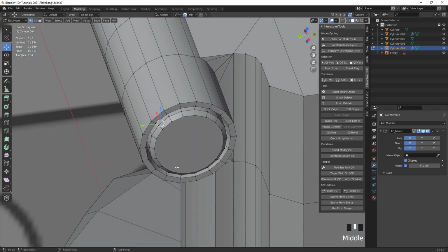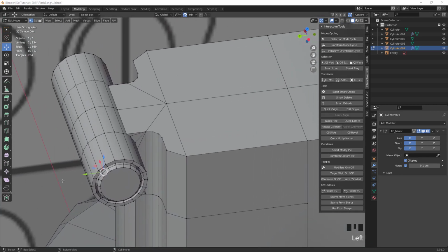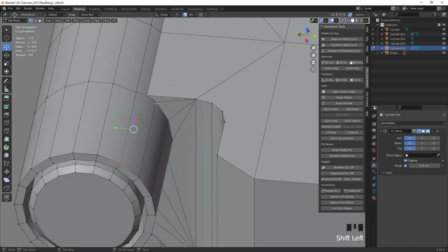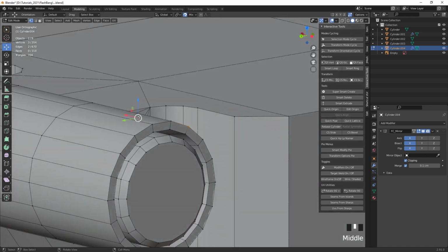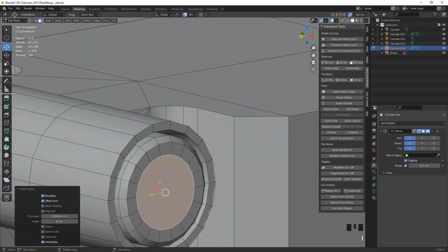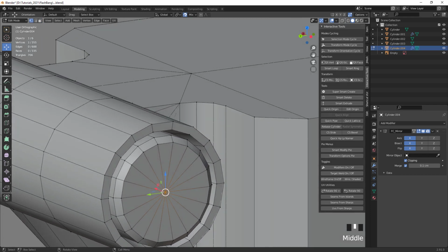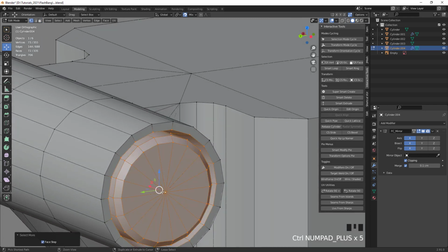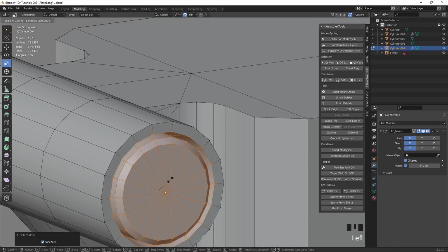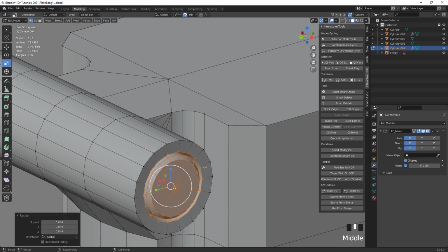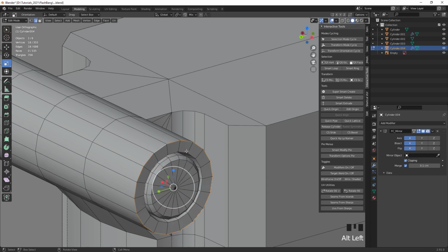And also here at the top we have another n-gon where we should already dictate the triangulation. So let's connect that, and then back here on that piece I'm gonna make an inset and collapse it, and then I want to grow the selection like that, and this whole element I'm gonna scale a little bit in because that was a bit too thin looking. I'm gonna go and turn off target weld, and now let's work on our lever.